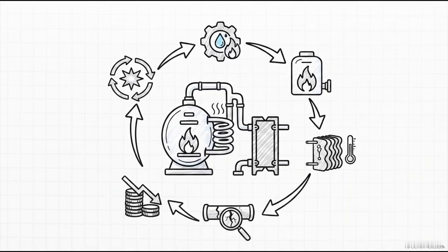If you're putting in way more natural gas but getting less heat out, you know for sure it's time for maintenance. It also allows you to monitor heat exchanger performance, making sure they aren't getting fouled or clogged up. By identifying energy losses, like those degraded insulations we mentioned, you are directly reducing production cost. Every single kilowatt saved is a penny earned. And all of this culminates in a massive improvement to overall plant efficiency.